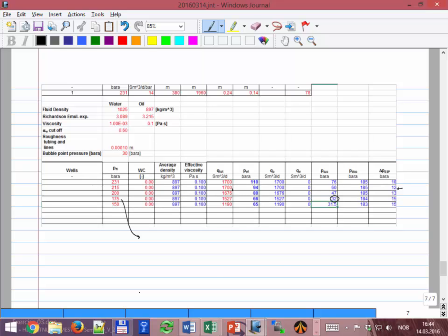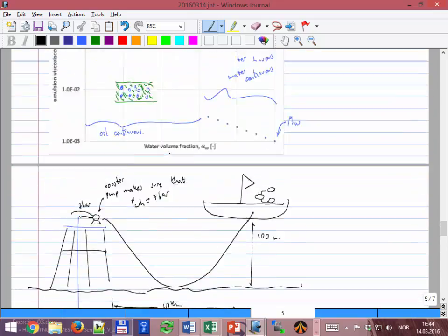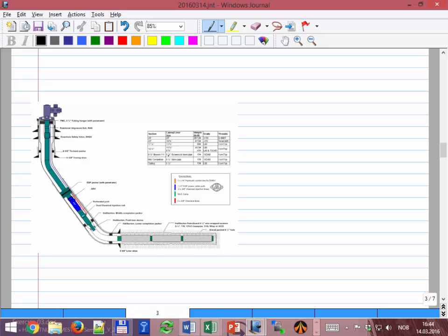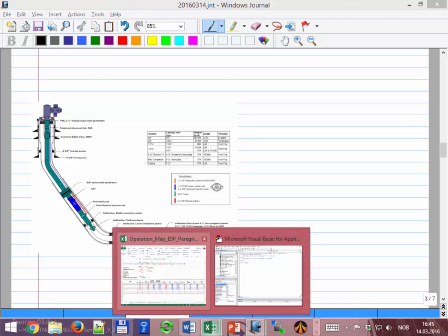But usually, especially in these inclined wells, these deviated wells, the common principle is that you try to put the pump as close as possible to the formation, without having problems later that it's going to get stuck when pulling it out or putting it in. So really the pump has to be all the time at the lowest point possible, as close as possible to the formation, in the deviated section. So maybe there is something to do there, but generally that's common practice.